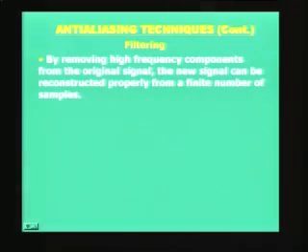We did say that aliasing corresponds to coarse sampling. Coarse sampling, whenever it is done without smoothing, typically results in the jaggies, or aliasing effect, or the staircasing effect. There will be high frequency components present in the signal, which is equivalent to saying that there are ripples or staircasing, which is the effect of aliasing we observe in computer graphics. A similar concept also exists in digital signal processing. So, we have to remove these high frequency components by filtering.